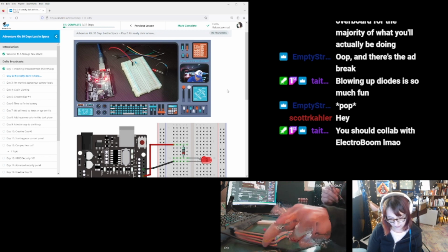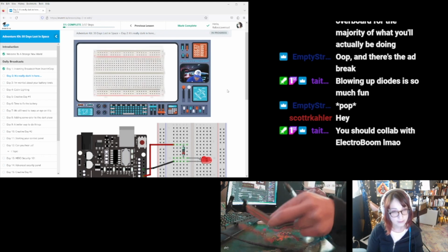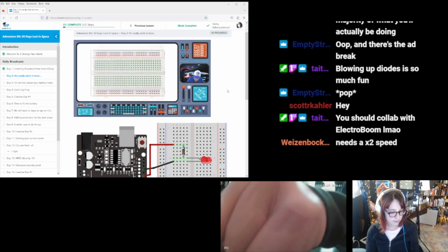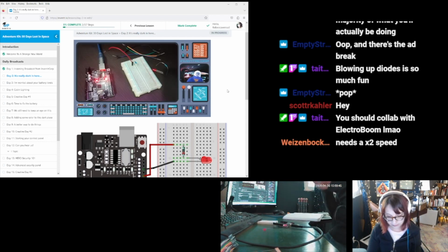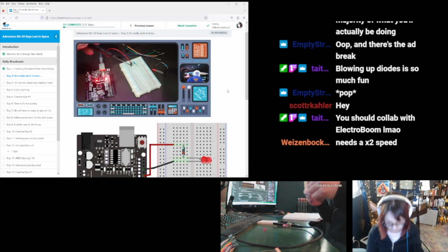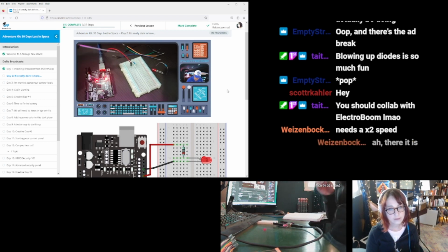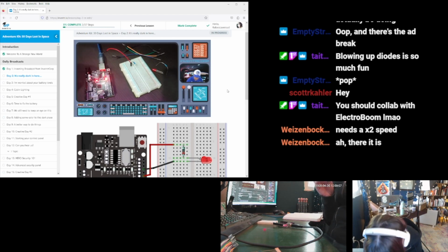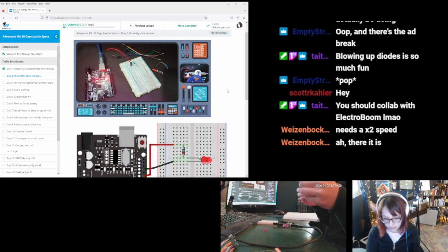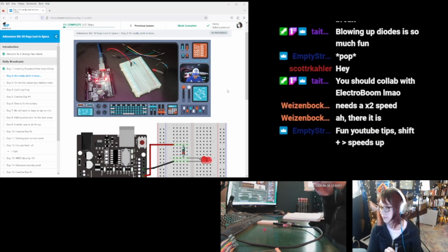And the reason why that's helpful is that the breadboard provides electrical connections between holes in the same row. So, for example, all of the holes here in row 6 are connected together electrically, or all the holes in row 5. It turns out that we've also got connected holes in vertical lines as well. This red and this blue vertical line are also connected. And although we won't use those today, we'll find that it'll be convenient for us in the future to be able to use both horizontally and vertically connected rows of terminals.